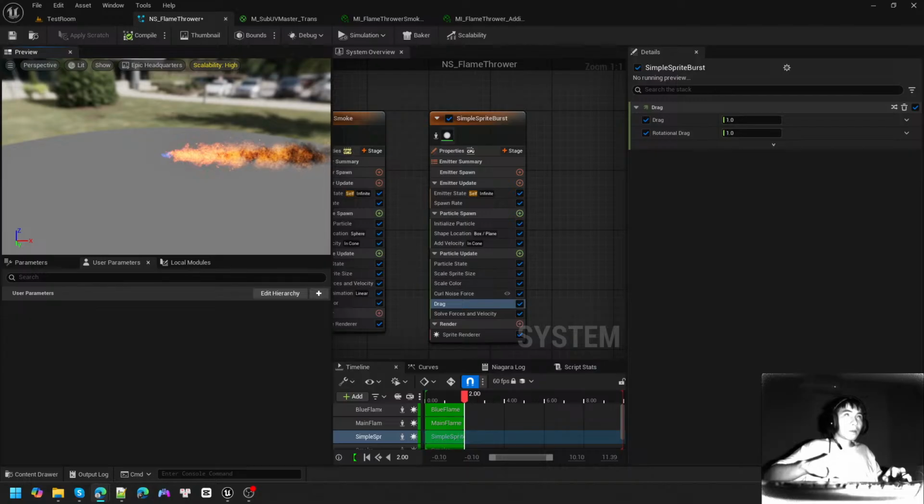The node I'm going to use is called sine remapped. Just to quickly show you what this node can do, I'm going to change the preview mode to a plane and right mouse button click this node, start previewing it. For the sine phase, I'm going to pass in the node time and plug it in. And you can see after that, the color of my surface begins to change. So this node allows us to output a value. And now you can see we can get this flashy effect.